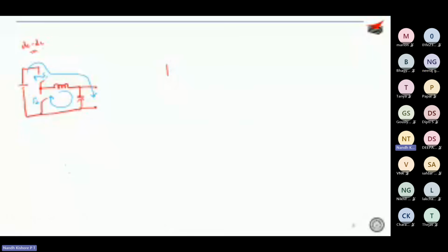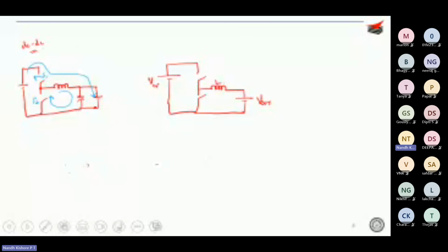Now you can also think about it as something like, okay, so let me complete it with voltage sources. I'm just taking voltage sources over here. Assume that this is V in and this is V out. Okay. So now the point is it all depends on how you modulate the devices. So let's say this is S2 and this is S1 once again. But the point is during the D period, I close S2. Because the switch is closed, the inductor charges, and when it wants to discharge, S2 gets open, so inductor current cannot change its direction. Therefore, it flows like that.